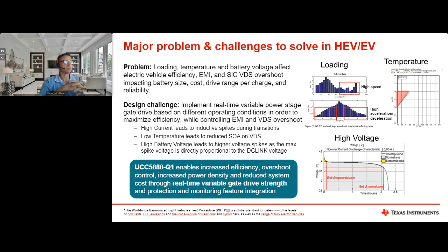So real-time variable gate drive strength will enable increased efficiency, overshoot control, increased power density, and reduce system cost by essentially enabling you to tune the inverter design in real time to address these challenges.